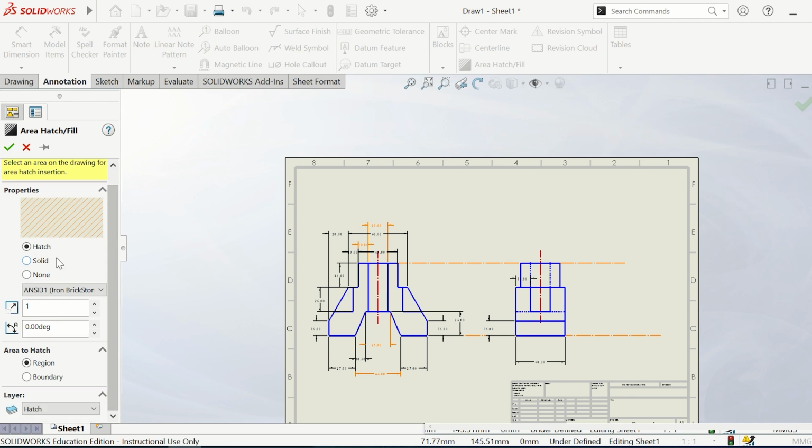Here you see the shape of the hatch, which in general we're going to place at 45 degrees. However, the hatching lines might change sometimes to dashed lines, or several types of dashing, or different patterns of these shapes, depending on the material that we are cutting in our section views.